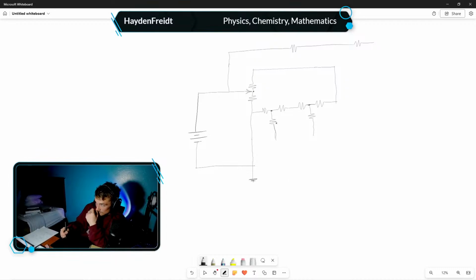So I'm adding these resistors for the purpose of determining when I want them to turn on, because you'll have a voltage across this resistor which, dependent upon this resistance here, will draw the desired amount of current and activate the gate to the transistor. I'll explain that better. I'm not really sure if I need a resistor here, but anyways, we can consider these like current limiting resistors.